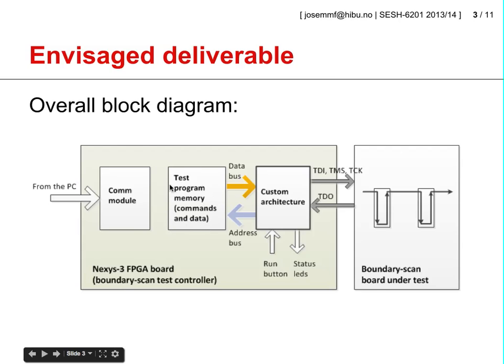Now, this test program comprises a number of commands and data that will have been received from the PC using a communications channel of your choice, and so the appropriate communications module will have to be implemented in the FPGA as well. And the whole system will be implemented in the Nexys 3 FPGA board.